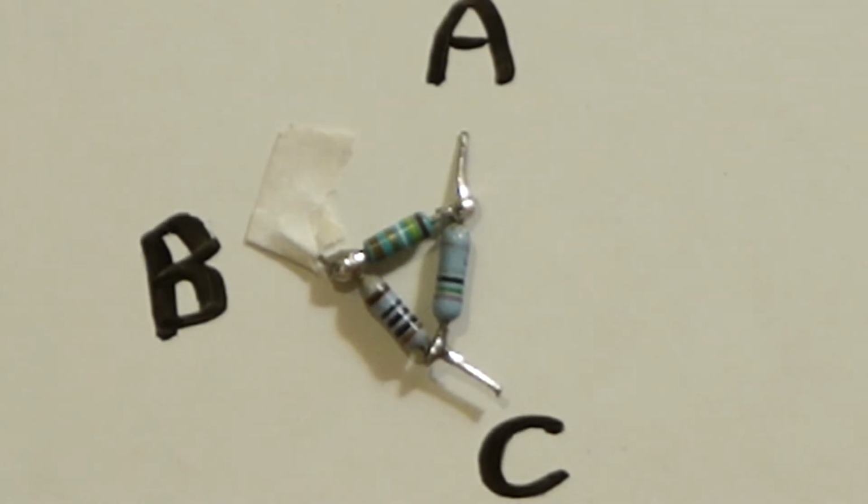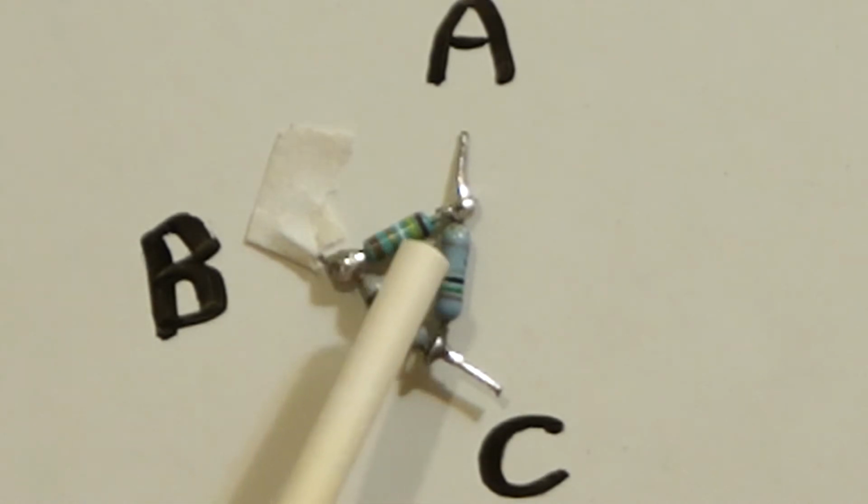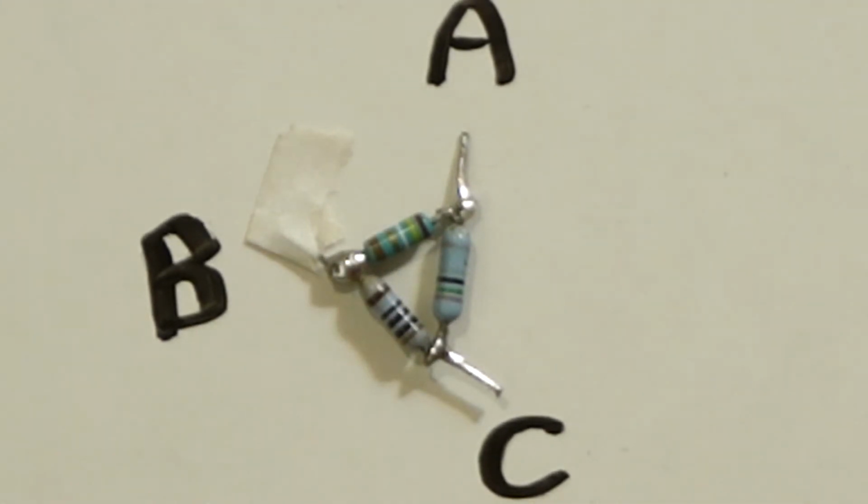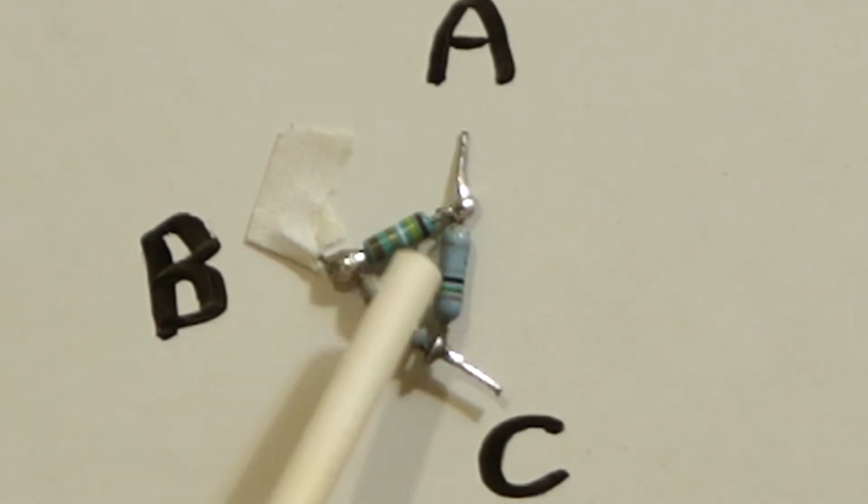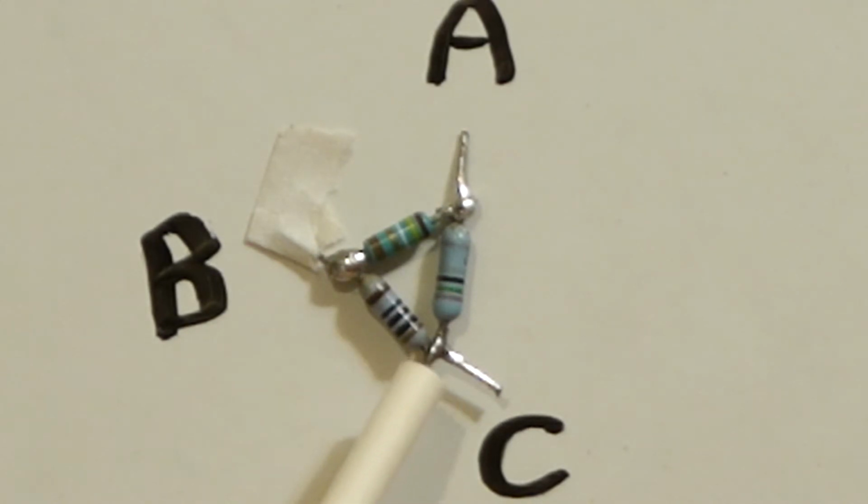Now, because they're soldered so close together, I wasn't able to break these resistors apart. If I was to take a diagonal cutter and free the one node so that I could measure the resistors directly, I'd never be able to get the network back together. There's a reason for having the resistors in such close proximity: it's to keep the lead resistances down and also keep them in thermal proximity of one another. This was in a precision amplifier network.